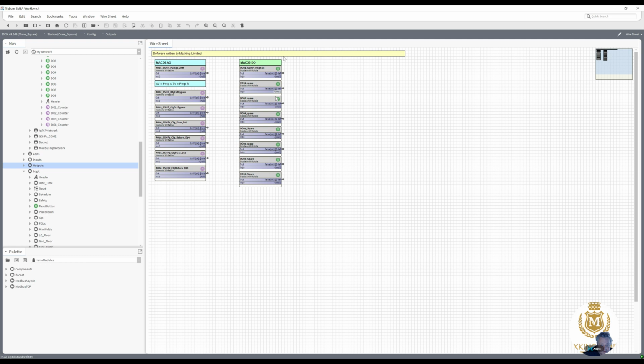And then ground source pump fail to put a light on the panel. So these are 0 to 10 volts, so 10 volts will open that valve and 0 volts will close it. And then these are 0 to 10, so anything between 0 and 10 volts to open the bypass.